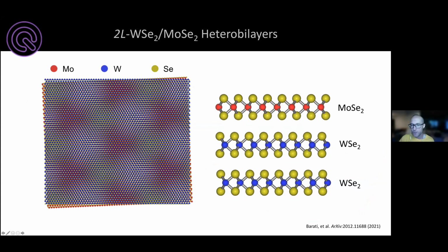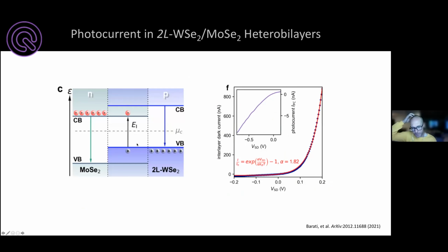And we used a new technique that's detailed photocurrent spectroscopy based on supercontinuum excitation. And we studied these devices, and what we found is that they're very, very good PN junctions. So if you think of a conventional PN junction, you can have the interlayer region where the basic excitation is this interlayer, lowest lying interlayer exciton. And the device essentially behaves as a PN junction when you have the chemical potential tuned right into the middle of the gap, just like you would expect.